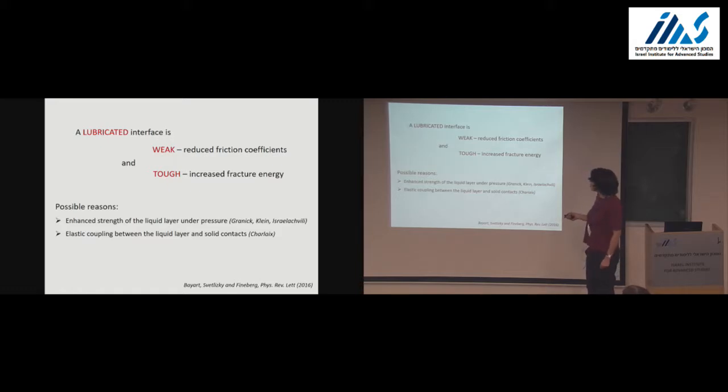But the reasons we thought about are that it could be that the lubricant layer is actually solidified under the very high pressure at the contact level, and then it enhances the strength of a contact. The other possibility is that there is an elastic coupling between the liquid layer and the solid contact, again enhancing the strength of the contact. If you want to know more about that, we can discuss after the talk, or you can open this paper here.